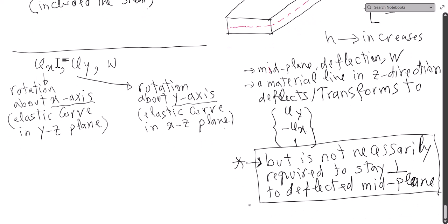Immediately you will see that the resulting governing equation will be three coupled partial differential equations, PDEs, for this plate theory. So a very small change in our requirement will bring more complexity, but of course richer in terms of predicting the behavior of the plate.